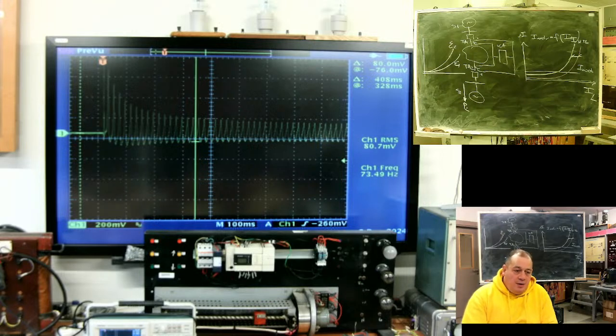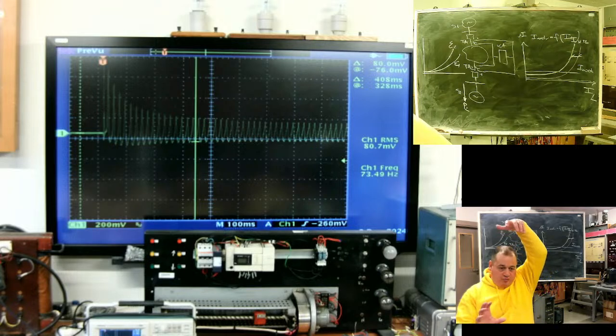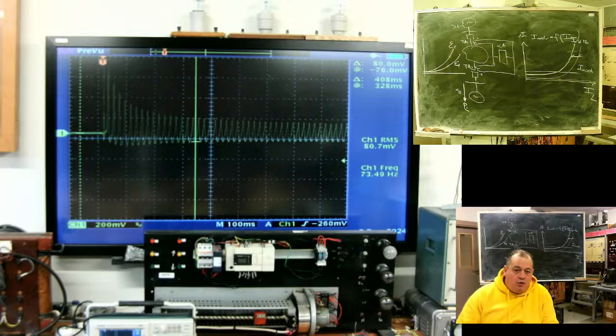Also, inrush current, this jump of magnetizing current, is the moment when windings are subject to mechanical force. It's the moment when an interwinding fault is possible. We need to operate safely. To operate safely, what do we do?